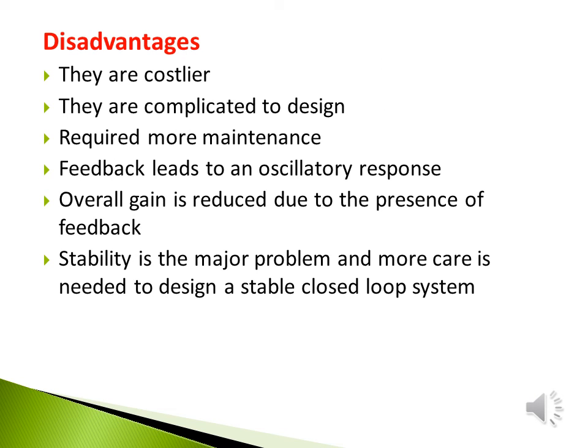These are the disadvantages of closed loop control system. First one is they are costlier. Second, they are complicated to design. Third, it requires more maintenance. Fourth, feedback leads to an oscillatory response. Fifth, overall gain is reduced due to the presence of feedback. And final one is stability is one of the major problems. So more care is needed to design a stable closed loop system.